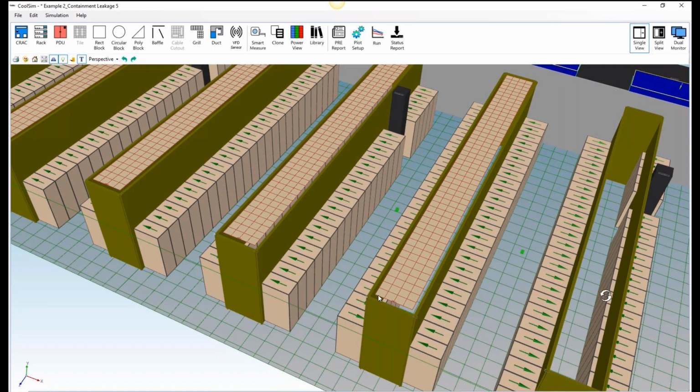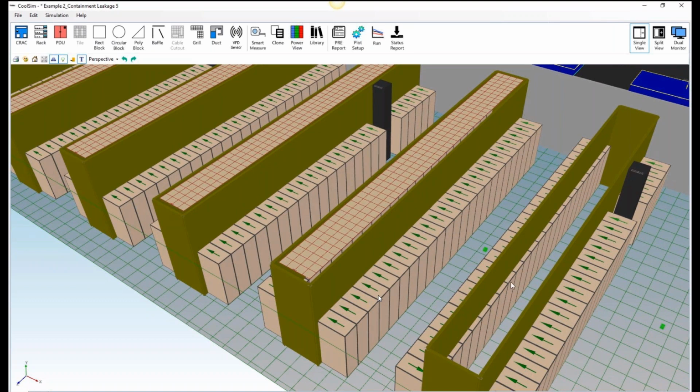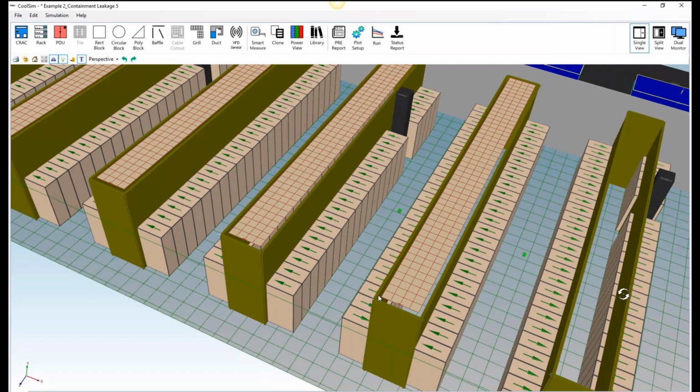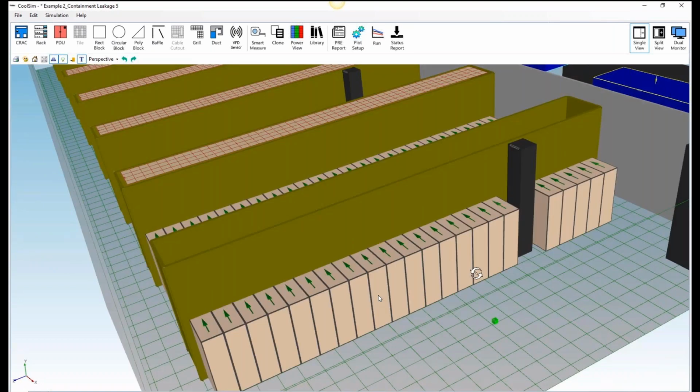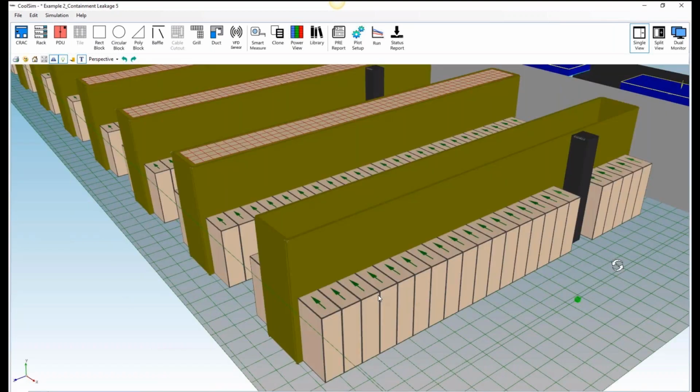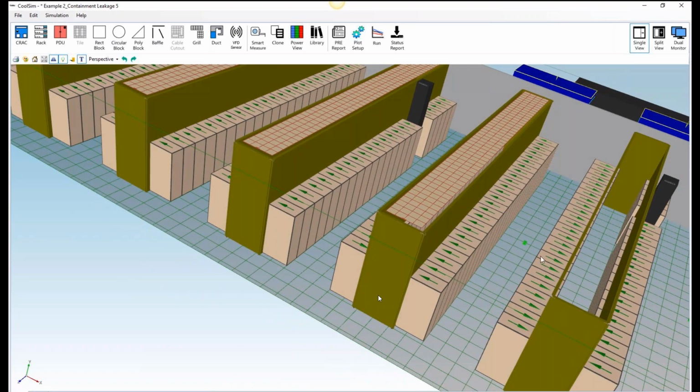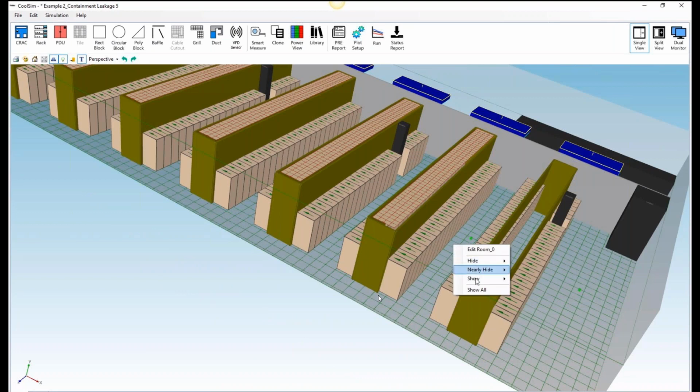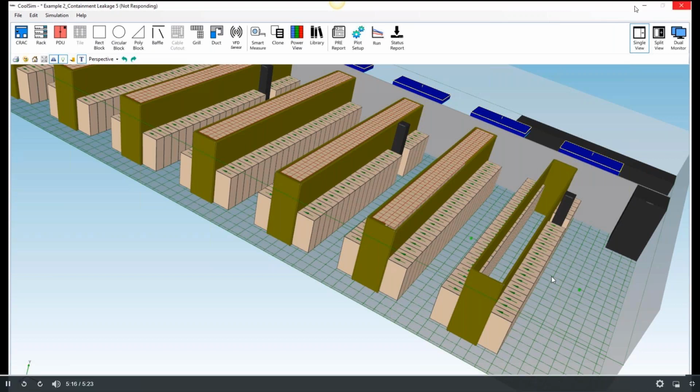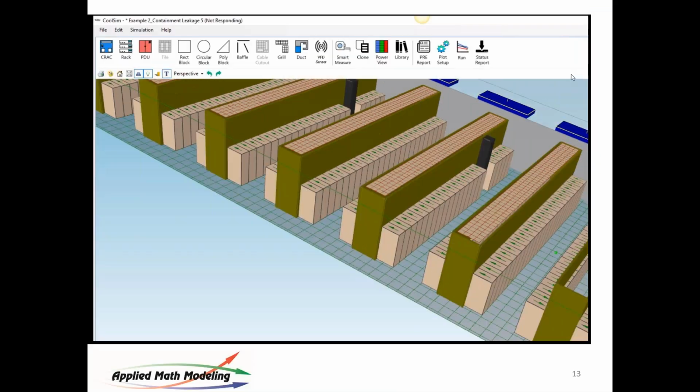And you see here I'm overlapping those returns, and that's important because you give the mesher a chance to put a surface on there, and they're slicing right through the racks. It doesn't matter. This model will run fine. So I wanted to show you quickly how to do that. It's extremely fast. So let me close this particular image here, or this recording.